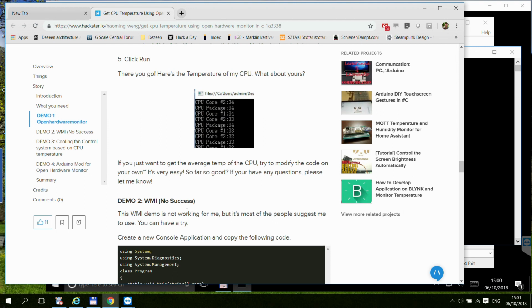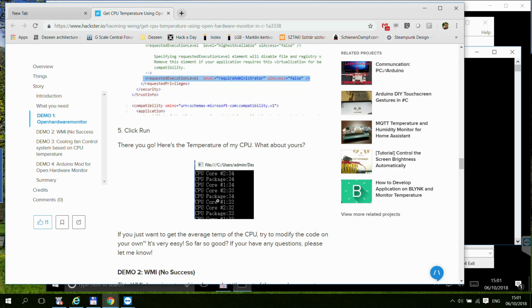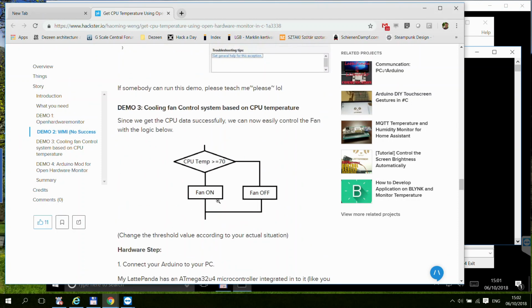So what I decided to do instead is, this console application is not going to do anything, just output the values into the standard output, which I can pick up from Node-RED, and from Node-RED I can talk directly to the Arduino, and again use one of the physical pins to control the fan, but also control that with PWM, not just simply switching it on and off.